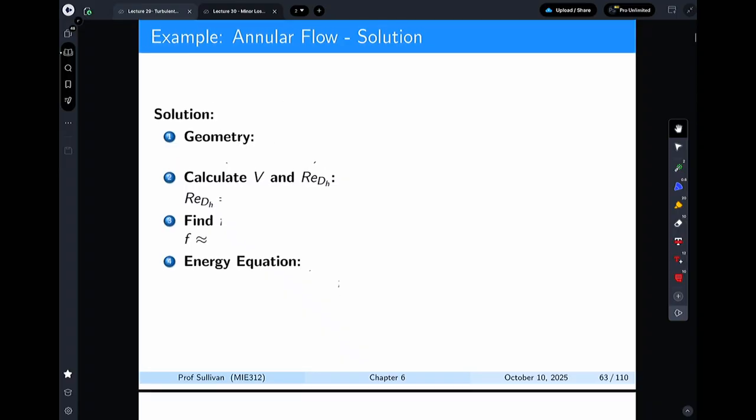So this is where, if I remember to do this, hydraulic diameter starts to come in. And if you remember the relationships we got last time, hydraulic diameter is 0.05 minus 0.03, and you get a number that is 0.04, so the average of the two.